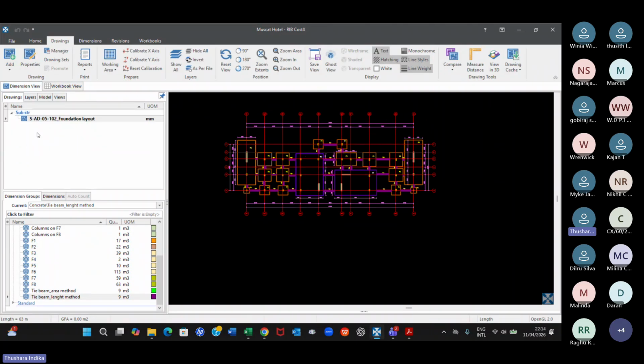So we need to upload a superstructure drawing now if you want to measure the superstructure slab. Right. And also we'll create something called zoning because now we have to measure the quantities zone-wise. Let's say ground floor to first floor is zone 1, right? So we create a zone because we want to keep our measurements separately from ground floor to the first floor. Therefore, we create something called zone. This is how you do that.